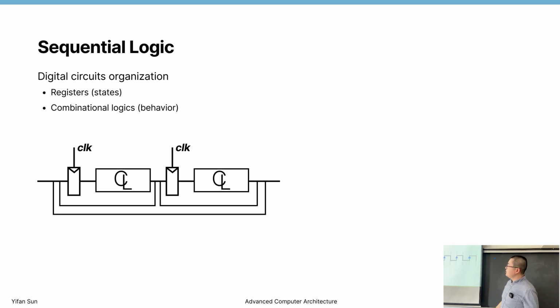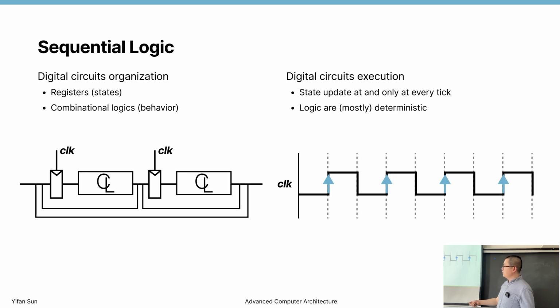So that means if we can properly model all the state and model all the combinational logic, which is mostly deterministic, right? If we can just simply repeat all this logic, then pretty much we can simulate every cycle's behavior of a computing chip, right? So basically we want to use this to simulate the synchronous digital circuit.